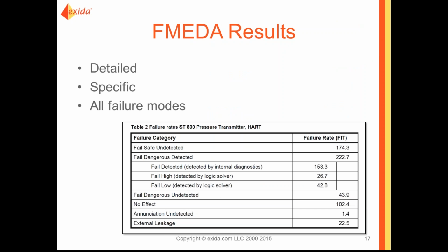The output gives you detailed results of failures, whether they're safe or dangerous, how they fail from a functional perspective, whether they fail high, fail low, or have no effect. And by having safe and detected numbers, you're able to get diagnostic coverage and create a pretty robust model of the device.